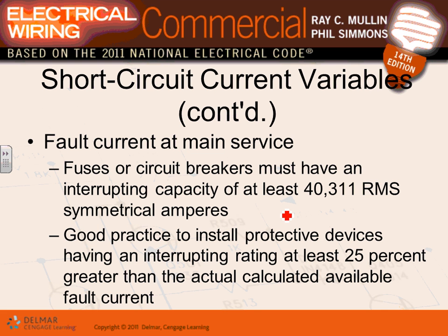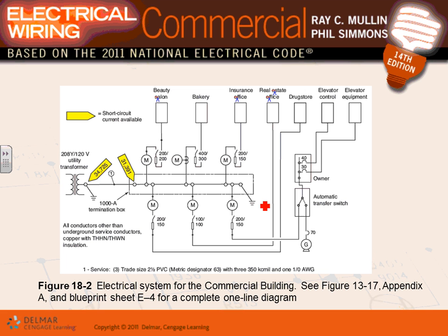Okay, the rest, guys. So if you have a short circuit of this value, 40.311, when you did your short circuit, a good assumption typically is allowing 25%. So you multiply this one by 1.25, and then you size the interrupting rating of your overcurrent protection device. That 25%, guys, allows you future expansion, adding more things and more load to your building.